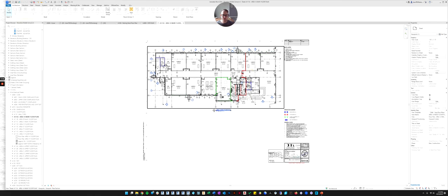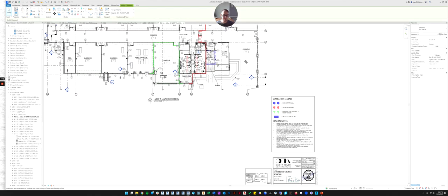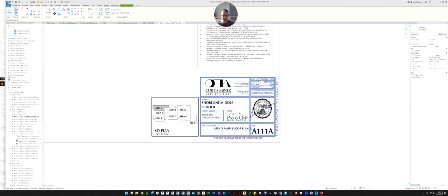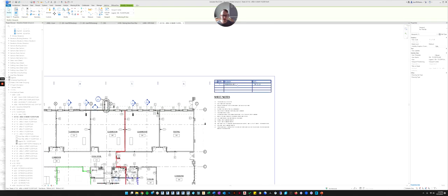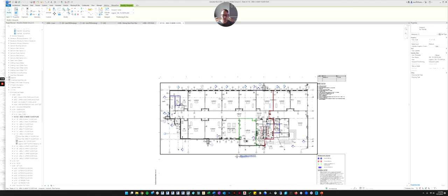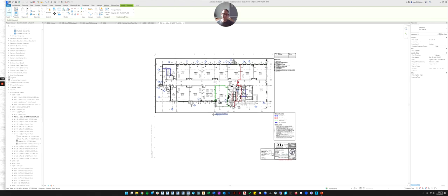So you can see there's different views on here. There's some legend components, but their title block is just one square down in the corner, similar to mine. And then up at the top, they also have revisions like me. And then they do a grid system across the top and the side. So a title block can vary, but we're going to get into editing and making your own title block for your own drawings. But for now, you simply need to know how we build a sheet: title block, views, project elements, and that's really it.